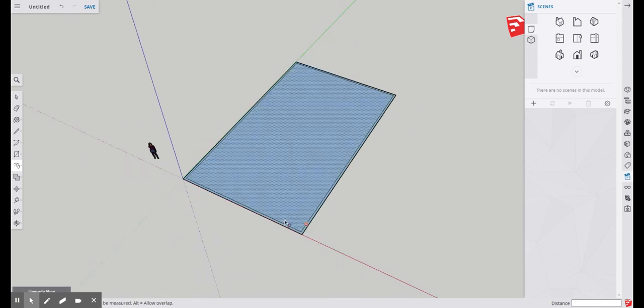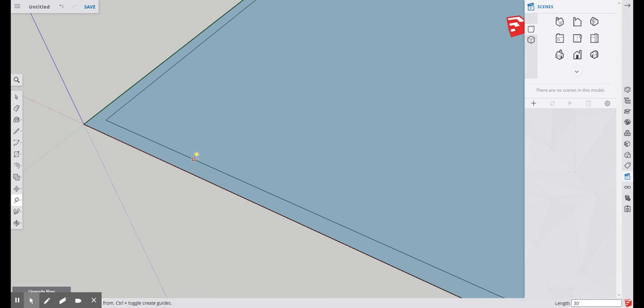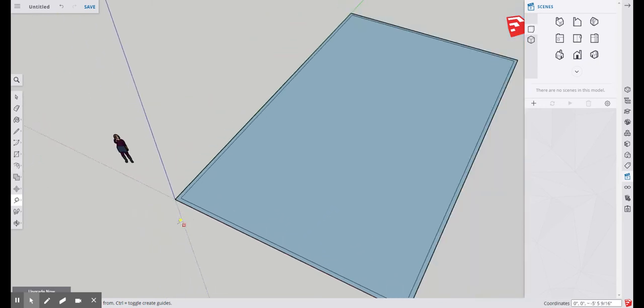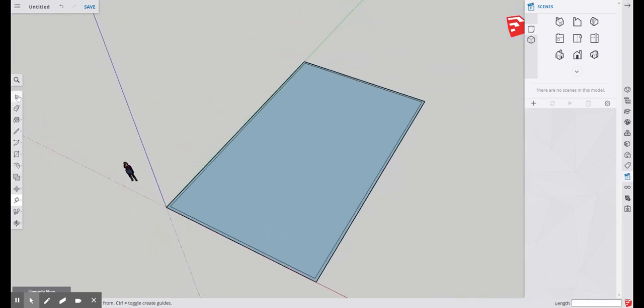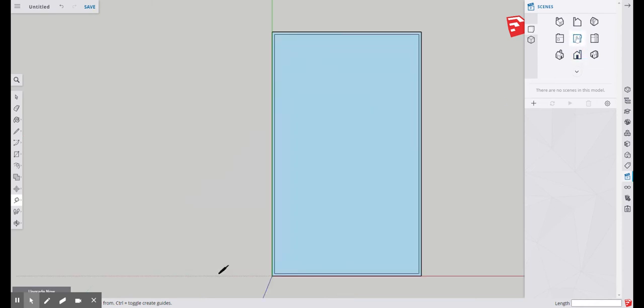Now we have our exterior walls at 6 inches. And we can make sure it's 6 inches with our measuring tape. Zoom in. I want to check from this point to this point, and it says it's 6 inches. I'm sorry if I said 6 feet again, I meant 6 inches. And just escape out of that. Okay. Now I want to proceed with making the rest of the floor plan, which is my interior wall. So I'm going to go back to this view and parallel projection.